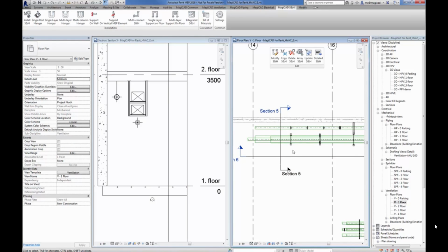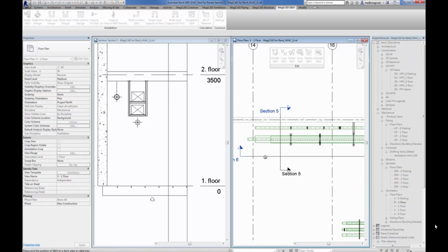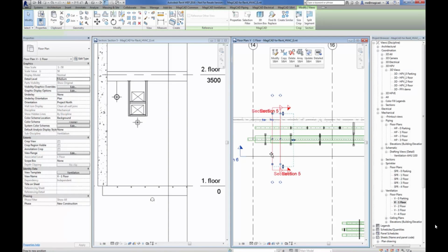In this case I created that hanger type over here, and by using copy now I can tell that I want to use this type and combine that with that duct and circular duct, and then click finish, and then it copies the first type.